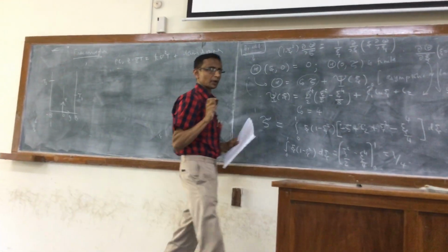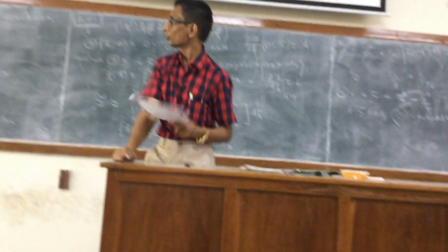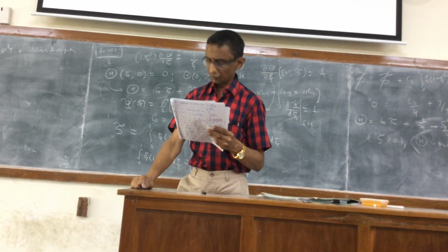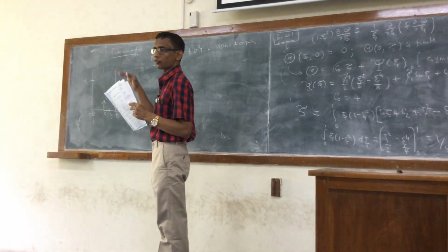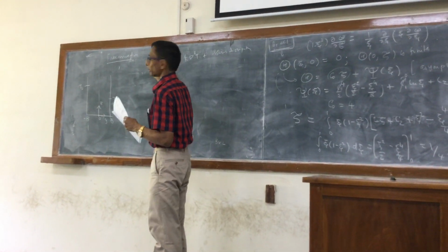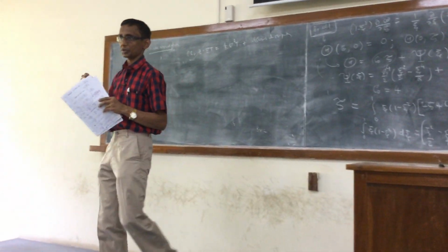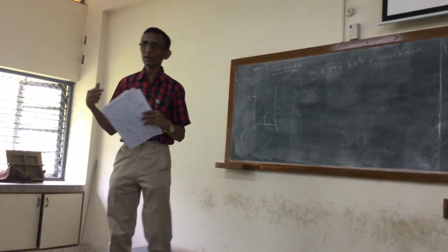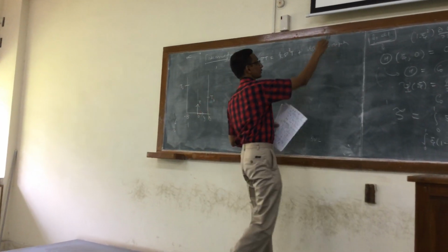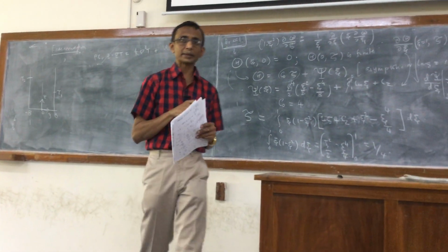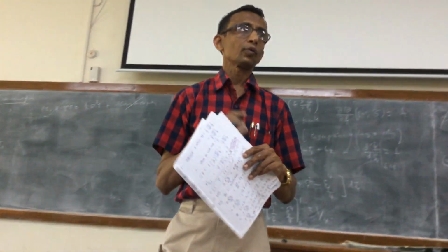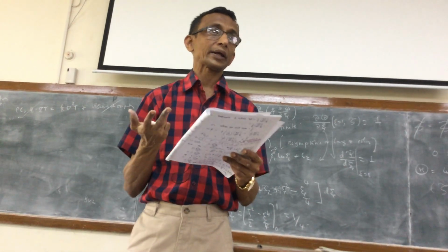Many approximations are considered here. Effectively, Lightfoot would say that because there is no forced flow, the forced convective effect will be quite negligible. Because of that, the viscous dissipation also can be neglected, right? And so it will be like pure conduction.